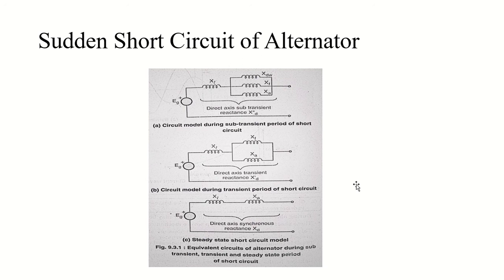Also again, if you have studied alternator and armature reactance, then you might have an idea about this, right? The resistance of winding is very negligible compared to the reactance, which is very high. So the current is highly lagging and the power factor is approximately 0.